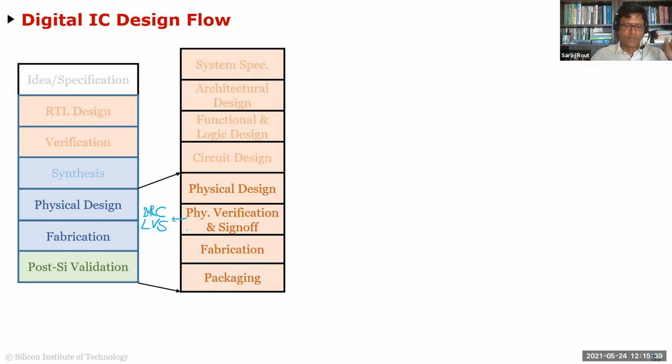For older technologies, say 0.6 micron, 1 micron or half micron in XFAB, the design rules are very simple: minimum separation, minimum width, antenna rules, and so on. But for 4 nanometer or 7 nanometer, the design rule documents are like 600 pages, so it's very complex.